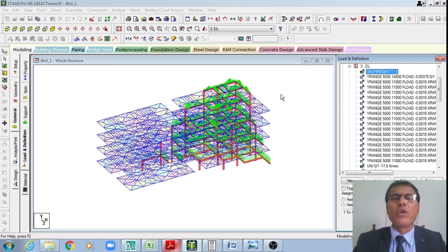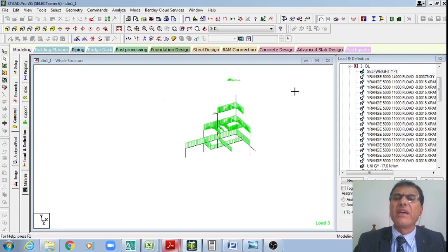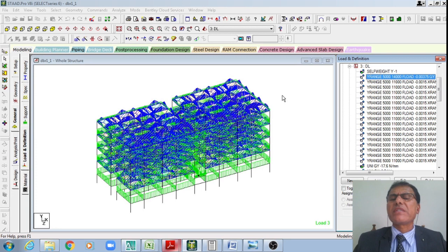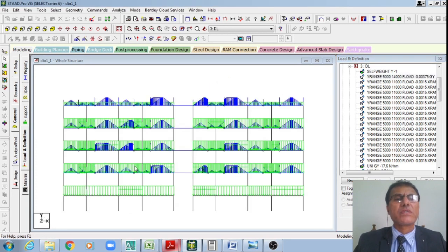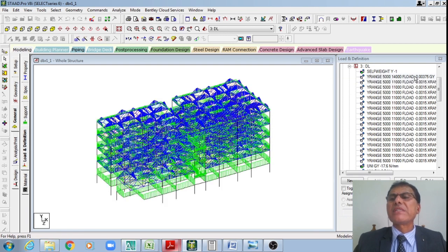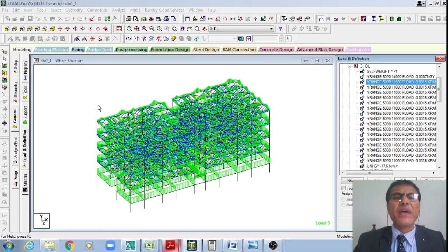Now once I see that, I will go to the top of all these, the red ones, the slabs. Then let me go to the top of these loads. Therefore, this is our 3.75 kilonewton per meter square at all the floors, starting from the ground floor slab to the top of the terrace floor slab. Ground, first, second, and terrace floor slabs all are having 3.75. Now this 1.5 is assumed extra. Now let me show that at a quicker pace, student. I'll show that, and I'll come to that.